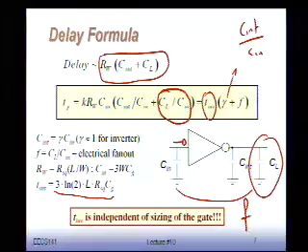And on the other side, the gate capacitance is given by the gate oxide. If I make my inverter bigger, I will basically increase both the gate region as well as the drain and source regions. So as a result of that, there's a fixed ratio in some sense, if I use the same topology, between the diffusion cap and the gate capacitance of an inverter. Okay? So that's that gamma factor.